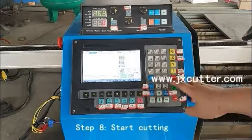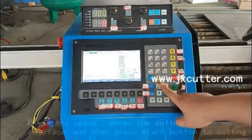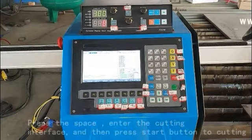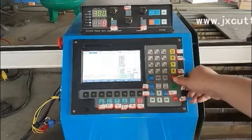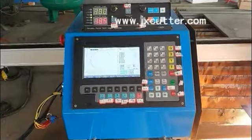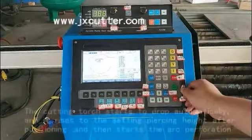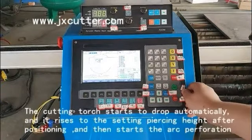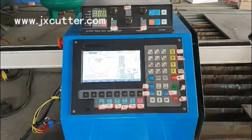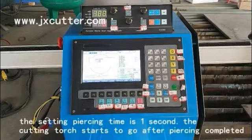Step 8, Start cutting. Press the space bar to enter the cutting interface, and then press the Start button to cut. The cutting torch drops automatically, and after positioning it rises to the set piercing height, and then starts the arc perforation. The set piercing time is 1 second. The cutting torch starts to move after piercing is completed.